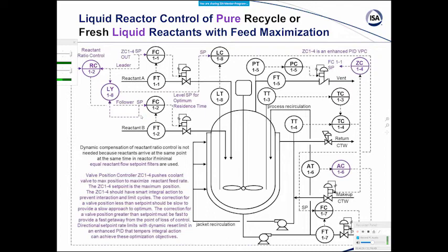So some people say, well, you should tune these flow controllers so that they have the same response time, so that if you're asking for a change in production rate, they both respond together. But unfortunately, that means if you have one controller that's particularly slow, and I don't know why, maybe it's the type of measurement, maybe it's the type of valve, maybe it's because it's noisy and you've got a bigger filter on there, you then make the other flow controller as slow as that.